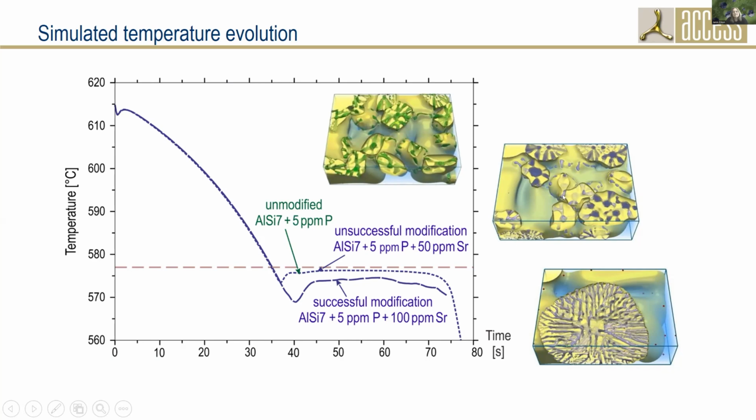And if we have a lot of nucleation, many nucleation sites, then we are always very close to the equilibrium eutectic temperature, and in this case it will be diffusion controlled, and the interface kinetics have no impact. They do not matter because growth is anyway hindered by diffusion, not by interface kinetics.